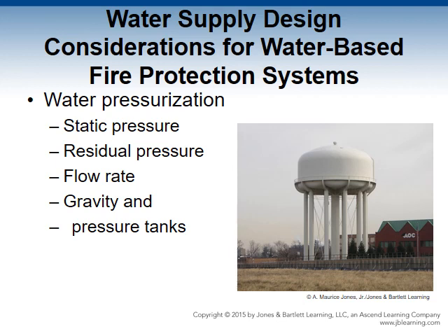Pressure tanks use compressed air to push water out of the tank and into the water-based fire protection system. These tank sizes generally range from 2,000 to 9,000 gallons, with water making up two-thirds of the total capacity and air the last third. Water supply must be capable of replenishing the tanks within 4 hours. The best location for a pressure tank is above the system piping, but some are installed below grade level.